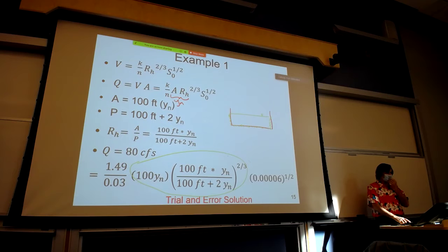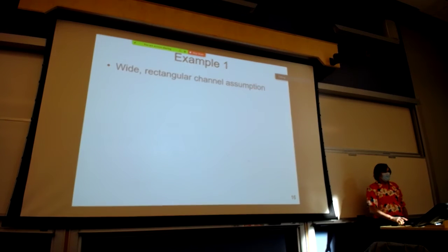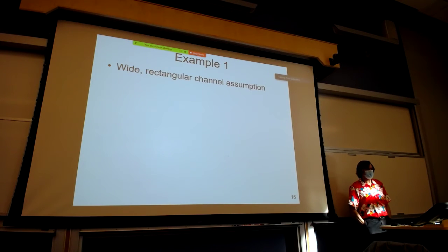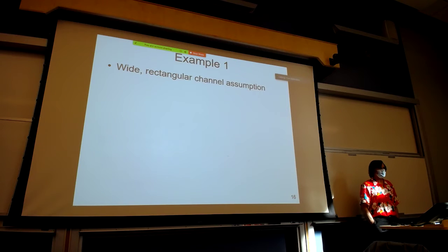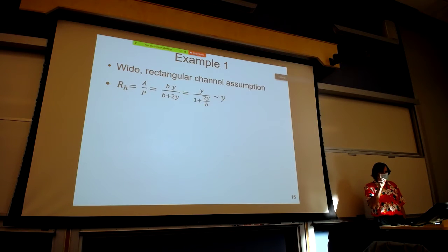Before we go to the trial and error solution, there's something called the wide rectangular channel assumption. For rectangular channels, and maybe even some other forms, this is not a bad first guess. But it's an assumption. You always have to check the assumption.